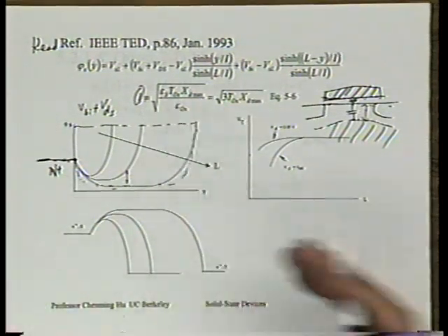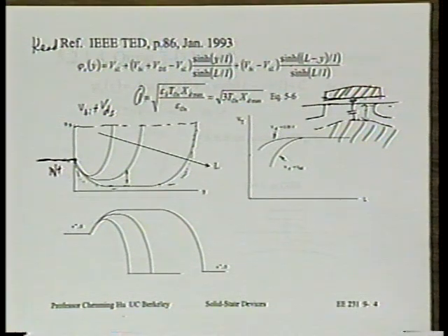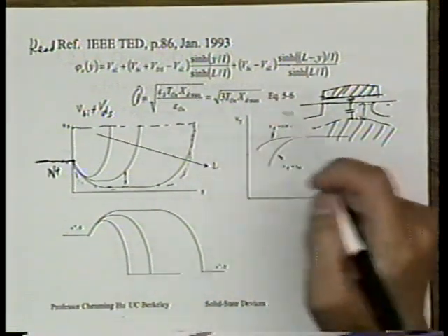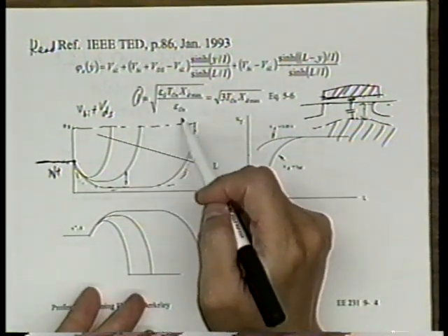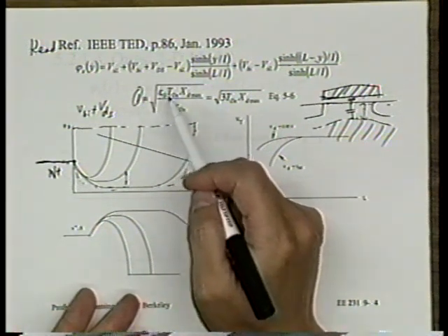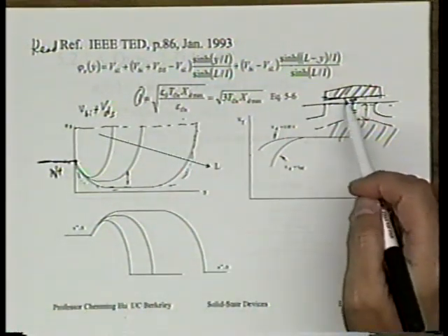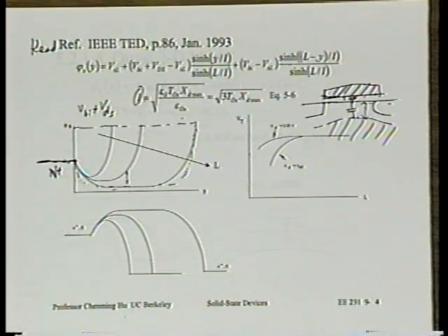xd max and Tox should appear side by side. Physically, they play the same role. I'll give you an example. Suppose xd max happens to be equal to Tox, with the ratio of epsilon, of course. You can even see why the ratio is here. We're talking about the electrical thickness of the top gate dielectric and the bottom gate, if they were equal. All right? If they were equal.